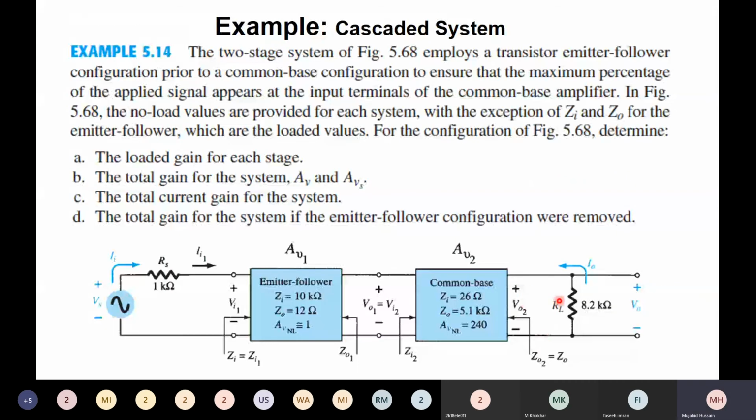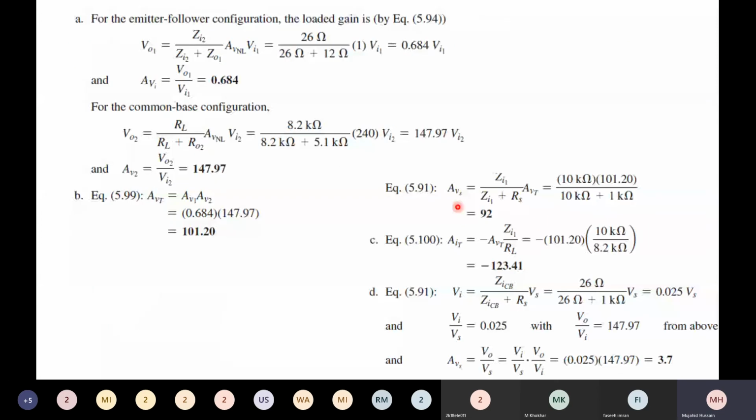So after substituting values and you find total gain, this is the overall gain. We said total gain, input impedance over the sum of RS plus Rin, the overall current gain. Similarly, you can find the rest of the values because we discussed in the last lecture Vin over IS, V naught over Vin. If you take the product of these two, you can find the overall gain.